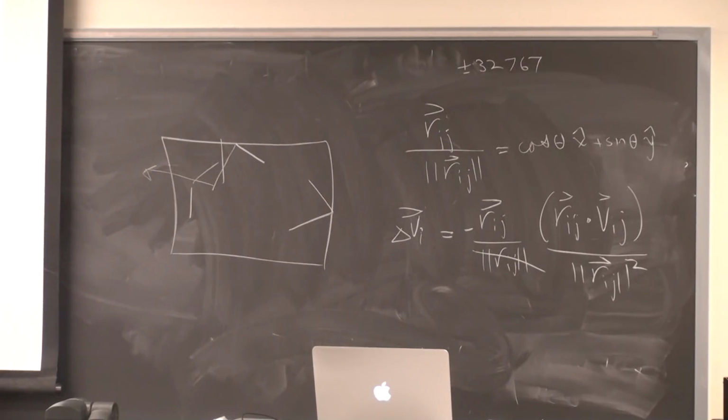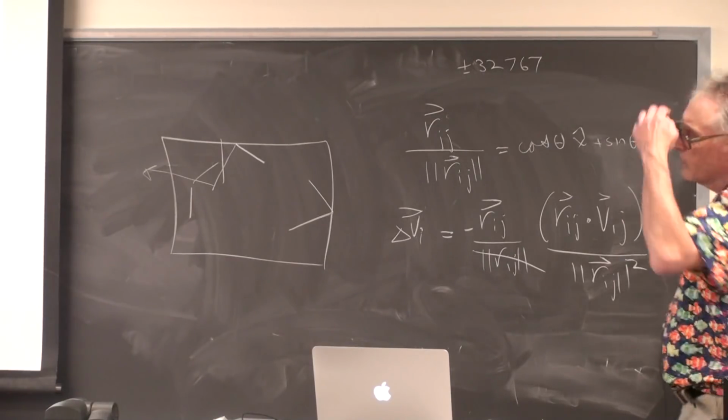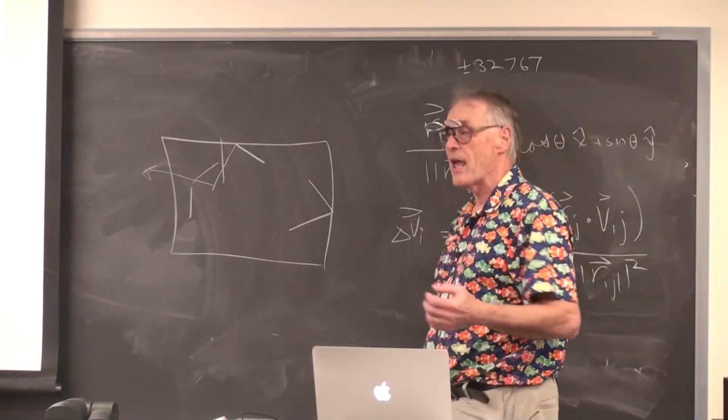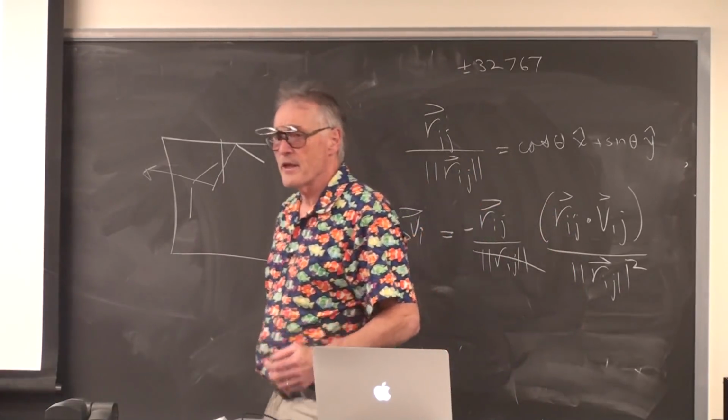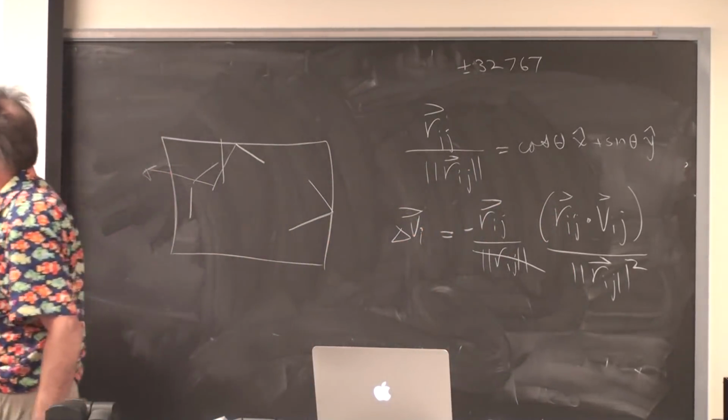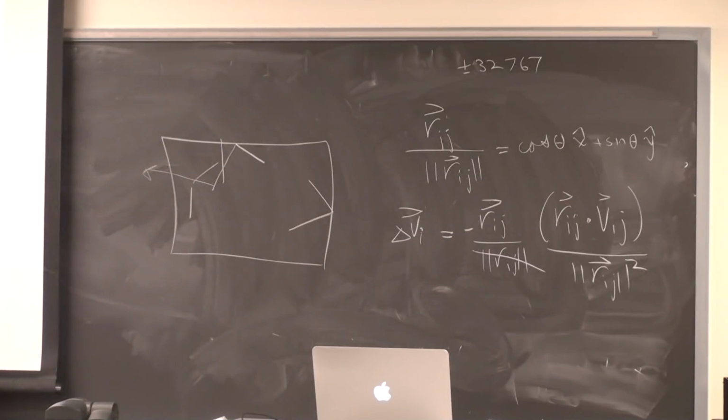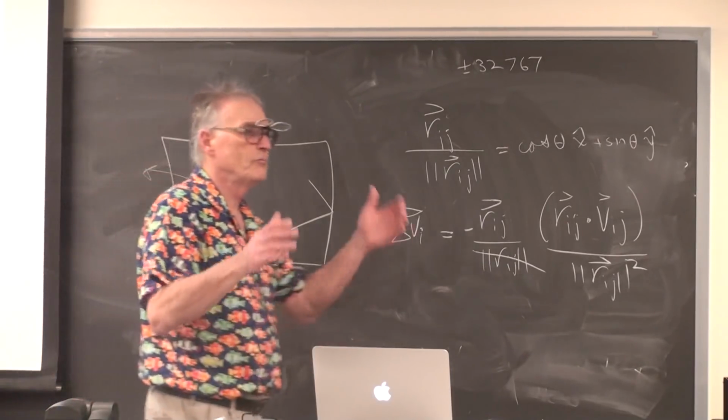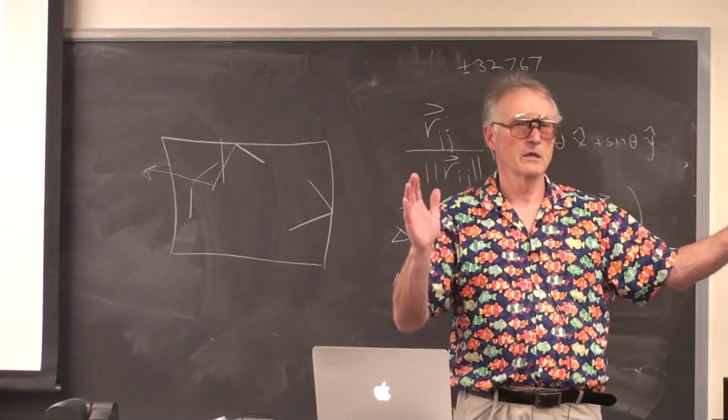What do you think happens if that goes negative? This argument goes negative. Well, I'll tell you what I think happens, and that is that the timer that's involved in this is an unsigned long, and so you're going to get a yield time that is about 2 billion milliseconds.